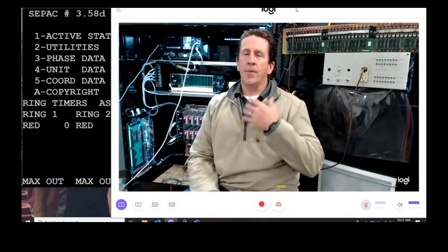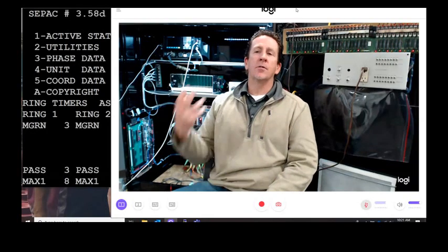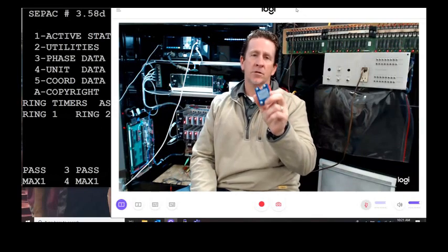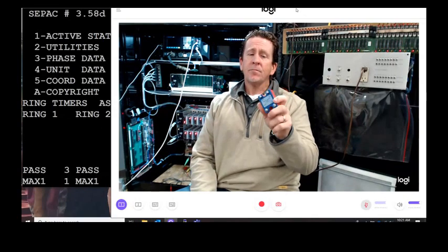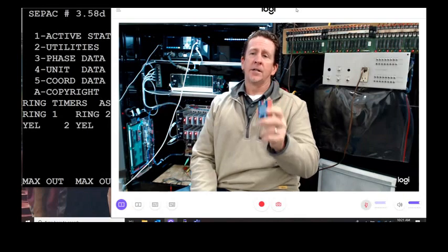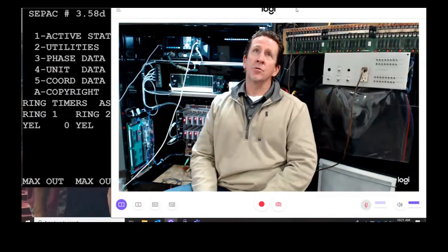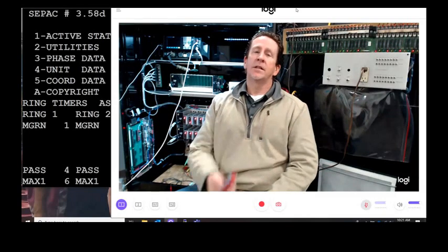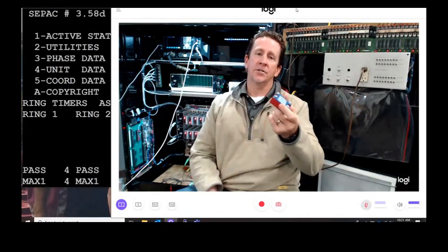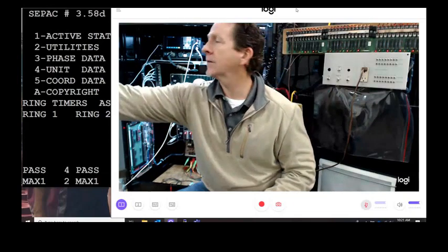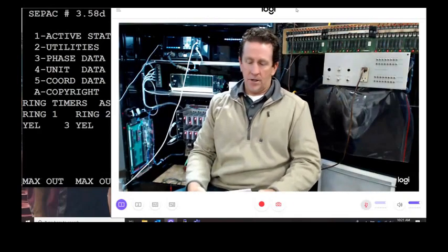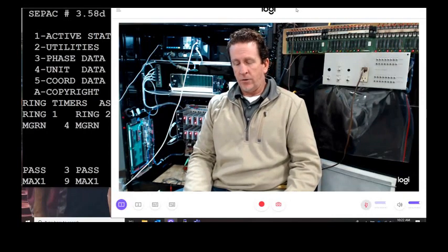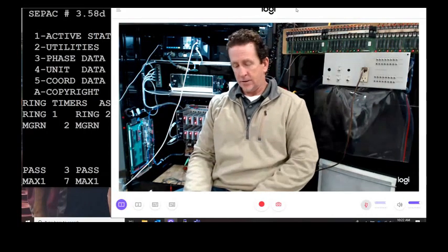But the point I'm trying to make is if you can't get it flashing through the flasher on the back panel, have a couple of these little cubes in there. They don't cost a lot of money. Some of our school zone signals will have a regular NEMA flasher in there. Other ones just have the little flash cube. These are handy because you don't need a socket and you can just wire it in there and it can sit right on the deck. So again, either the flash cube or the four-way stop signs, whatever works for you guys.